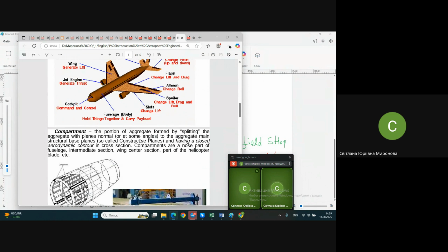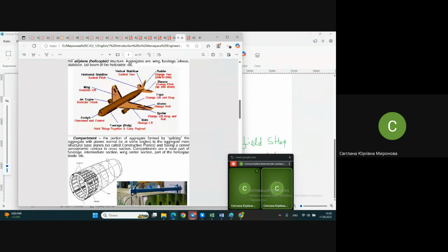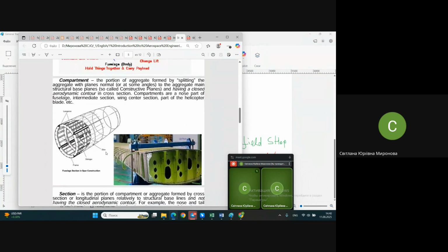Well, but as I already said, it's not convenient to assemble big multi-part components, aggregates, at one working place in case you have a big manufacturing program. In case you need to produce only one airplane, no one will bother with organizing separate working places divided into little pieces. More probably it will be 5 stations like wing, fuselage, and so on, literally. No one needs to spend additional money and time on preparing manufacturing with various tooling at all.